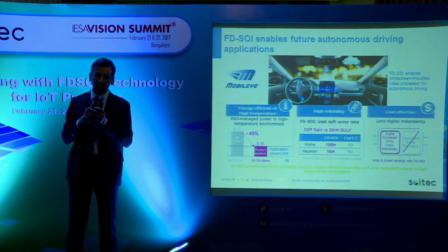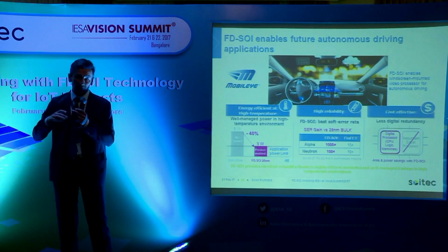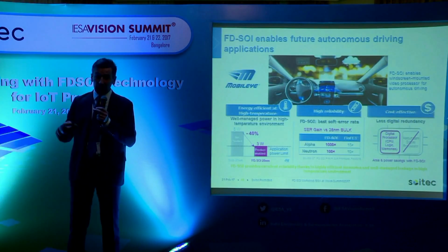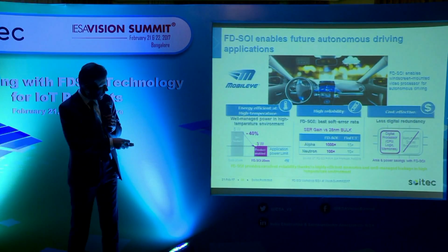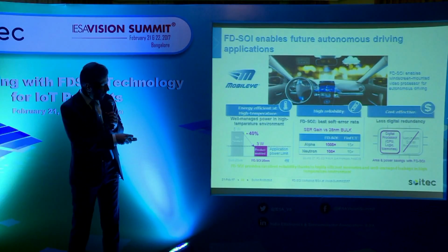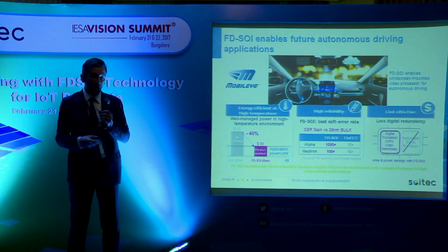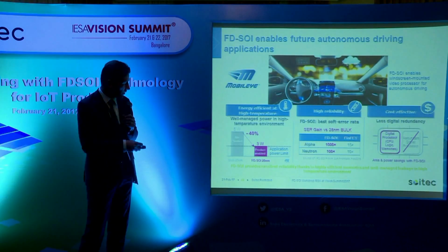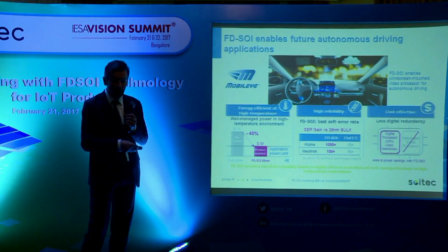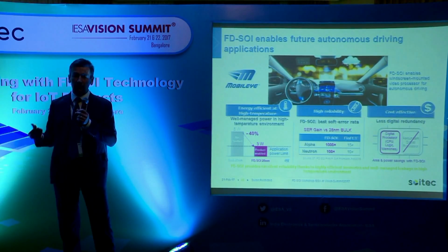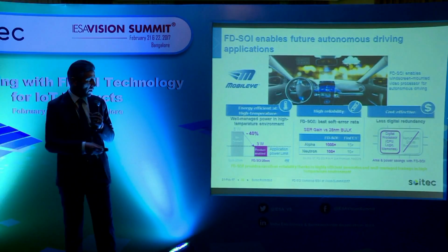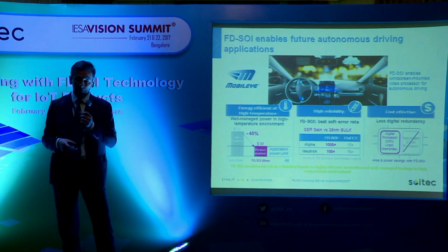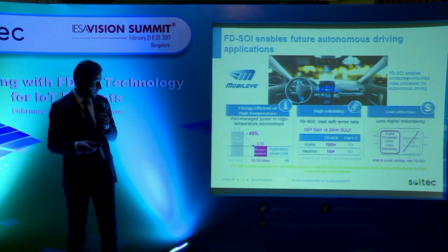So there is a limit that this chip can consume not more than 3 watts, but still deliver a lot of performance. So you see here that this 5-watt chip was a no-go. There wasn't a solution for this application. With FDSOI 28 nanometer, which performs at 3 watts, it's opening the door to this specific application. So it's a game changer because of the power consumption for this specific image processing application.